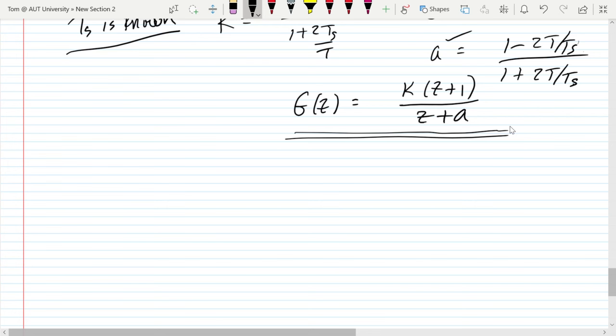It means the output just saturates, just goes up to a huge number. So for a stable analog system, you must get a stable digital system. And the bilinear method guarantees it, whereas the other methods do not guarantee it. So that's why I say use this method if you're going to convert from S to Z. There are other methods as well, the pole zero mapping method, the impulse invariant method, and a few others, and again, they're all lectures in their own right.